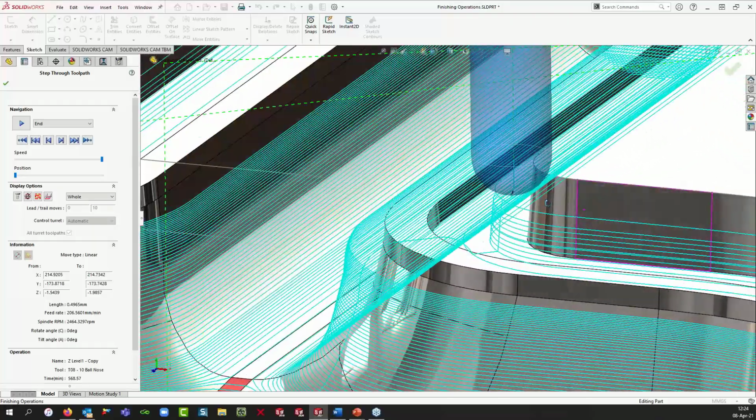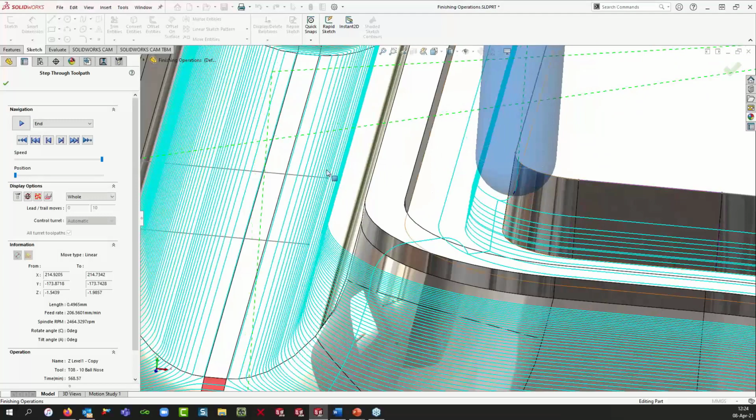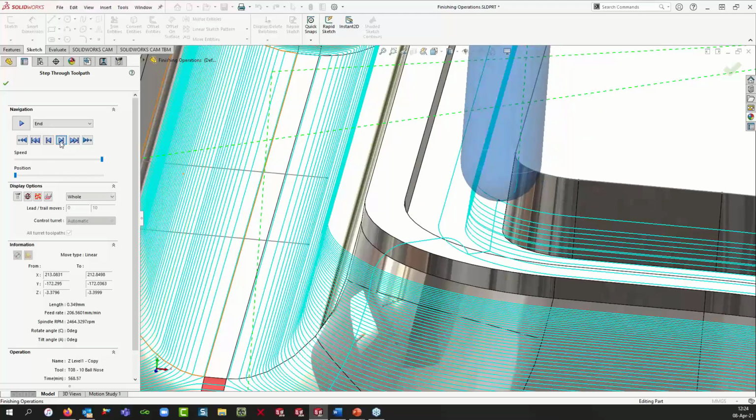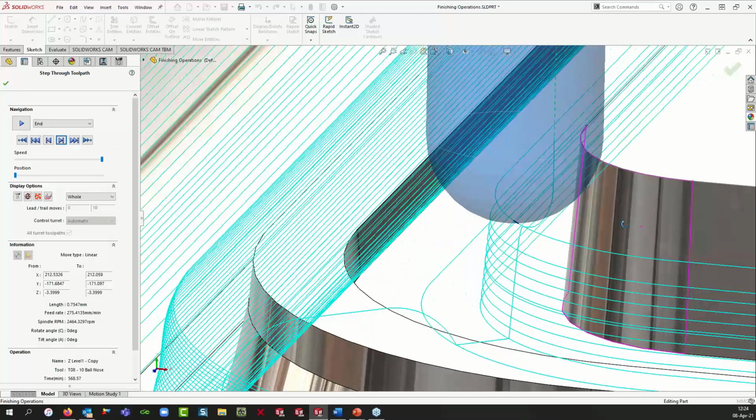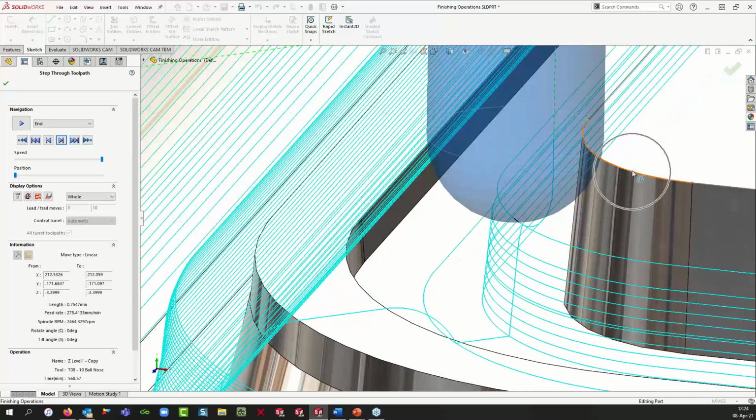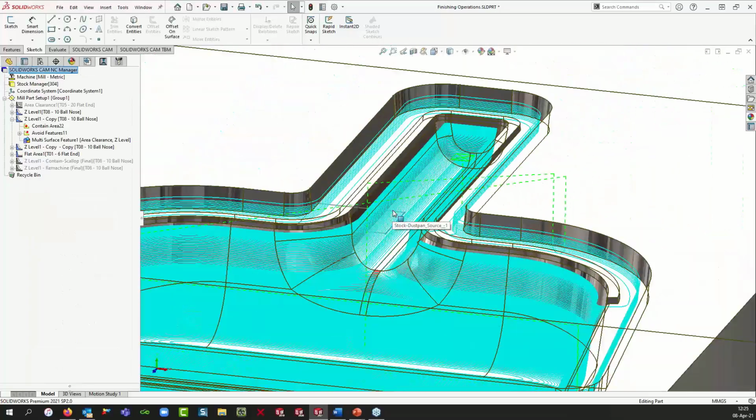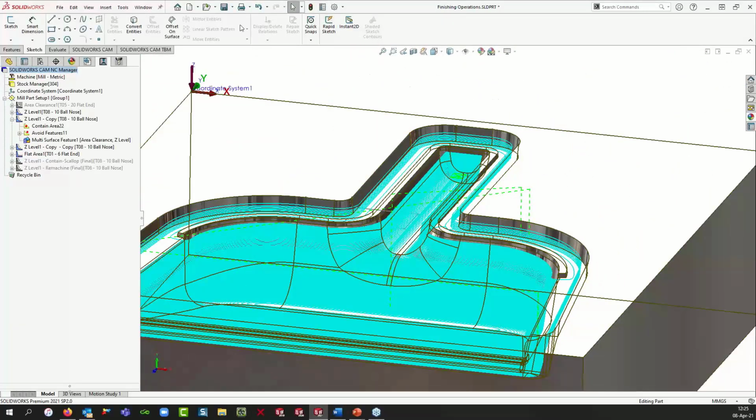So you might run into a situation where you don't want to have the initial movements of your finishing tool come in right where the edge of the model meets. There's some applications where, especially with mold tools, you want a nice sharp edge, or maybe it's creating a shutoff area. So there's actually a way around this. It's one of the tricks that I've come across in the past few years as a machinist. So why don't I go ahead and save this?